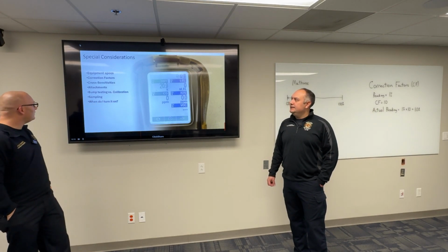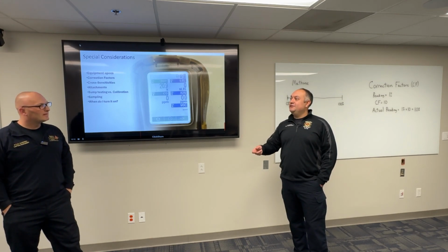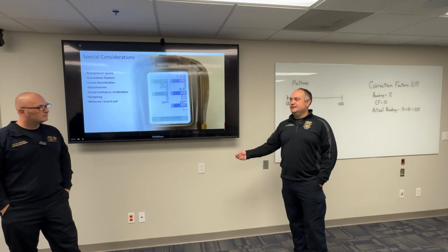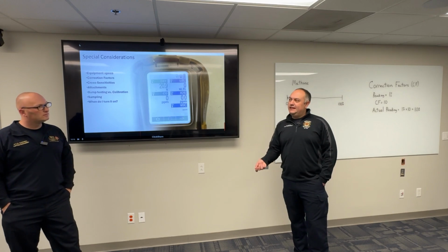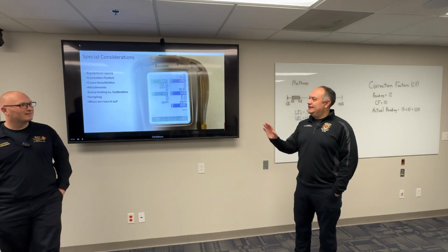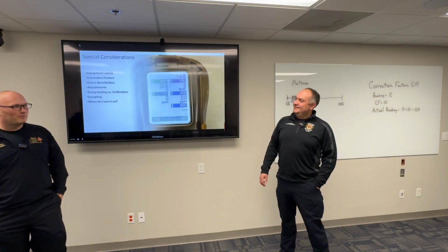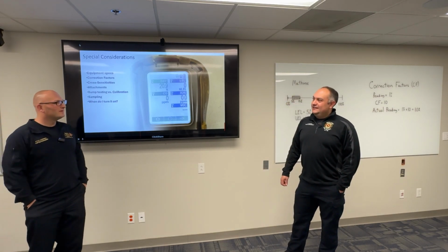Absolutely. And something else about that too, try and keep the probe, especially if you're using an attachment, out of liquids, because we've had it before where somebody accidentally put it in liquid and it sucks it up, and that thing's out of service until we get it cleaned. I can imagine. And they're hard to clean, I'll tell you. And you probably ruin your sensor, and those things are not cheap.